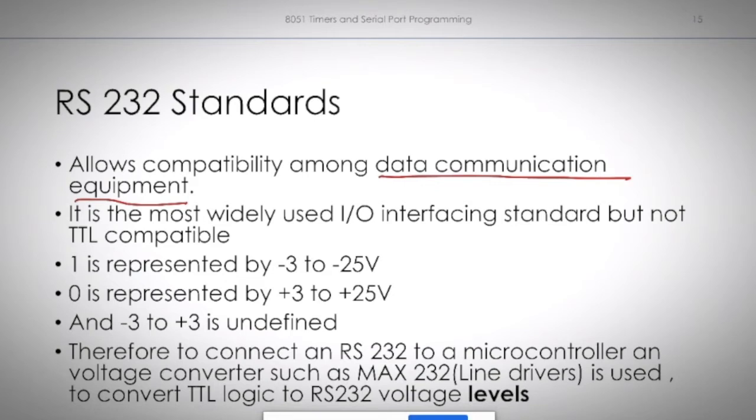That is because both ICs are compatible in voltage level. Suppose the first IC's output high is represented by plus 5 volt. The second IC's input high will also be referred to as 5 volt. So if you connect 5 to 5, both will consider this as a 1. That way, there is compatibility.